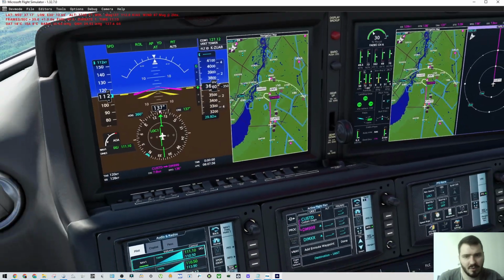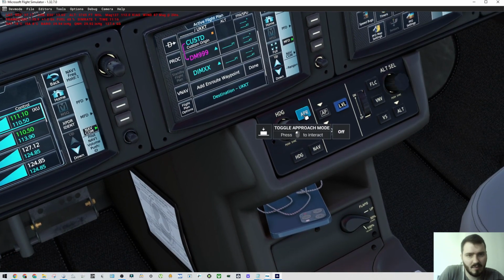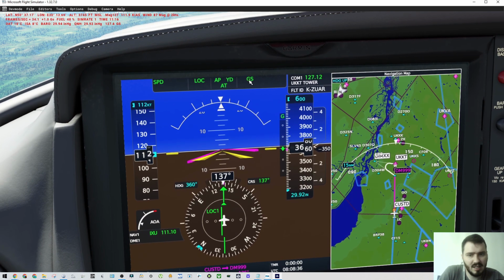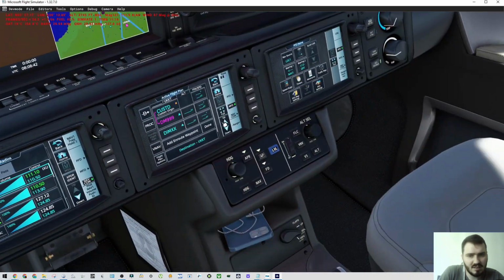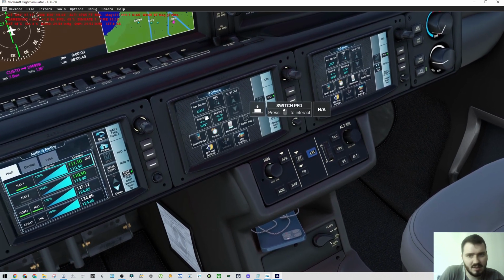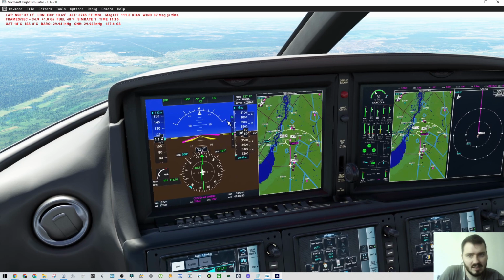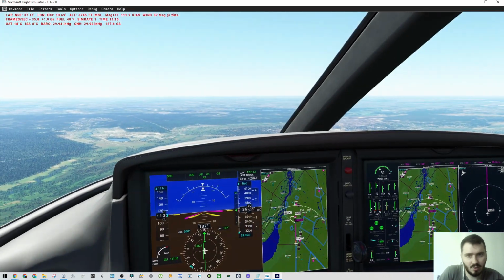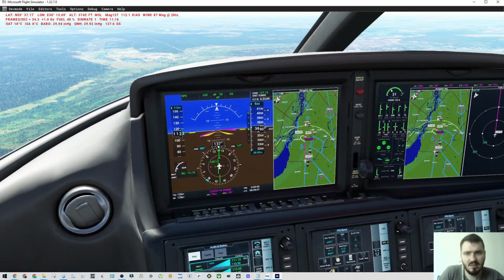And for approach we will use autopilot. I will turn on approach mode, and you will see that immediately we are on localizer and glide slope are captured. So I just come back to approach. For navigation I will click nav source localizer 1, and when I turn off autopilot I expect that the aircraft will automatically land in the place that we need, so on the runway. Let's go. Where is turn off pause?